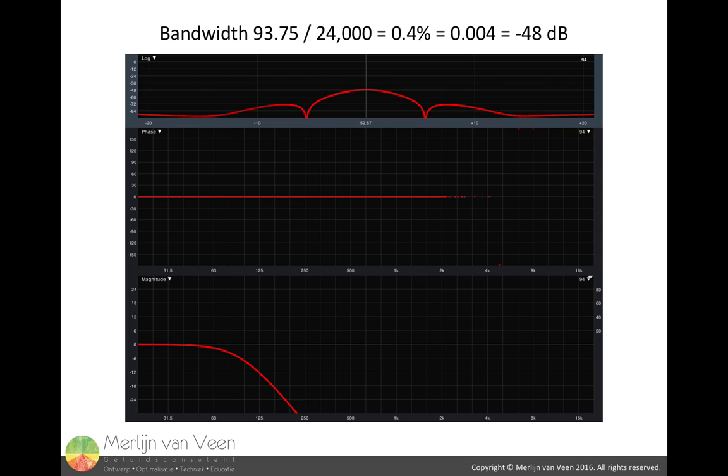Each bandwidth reduction by an octave results in an additional 6 dB drop of the impulse response. Notice the equal and symmetrical amounts of pre and post ringing, characteristic for linear phase filters, and the widening of the impulse response, indicating low frequency content.